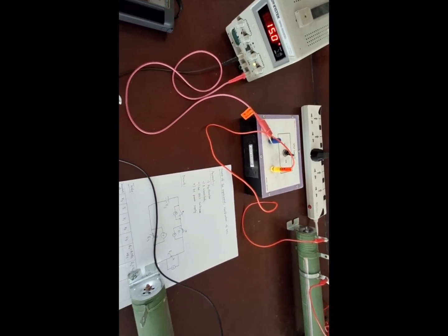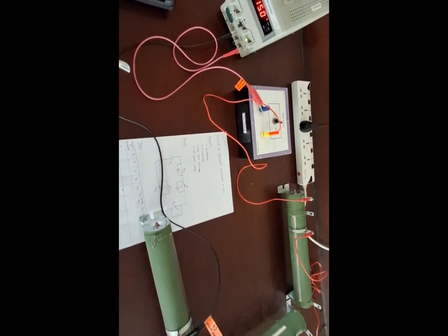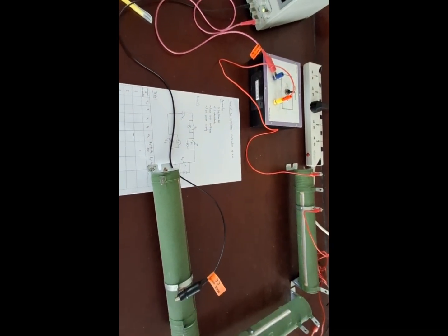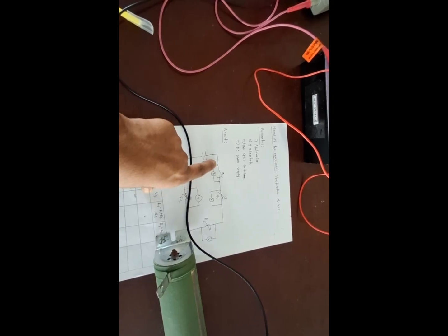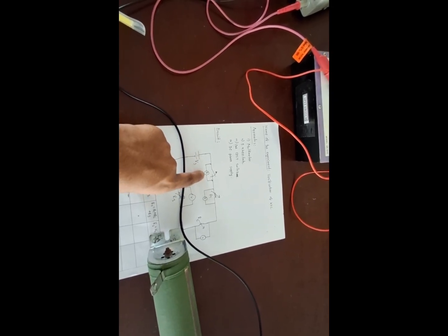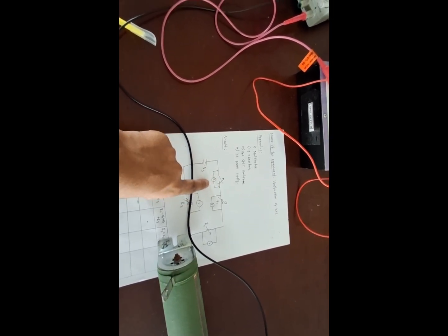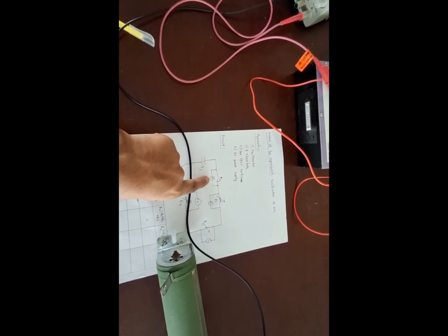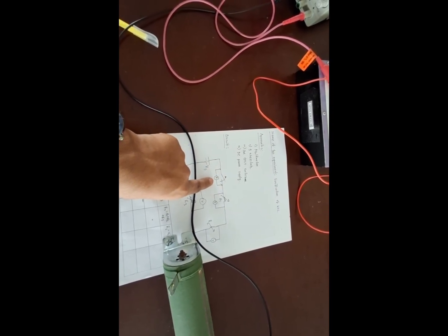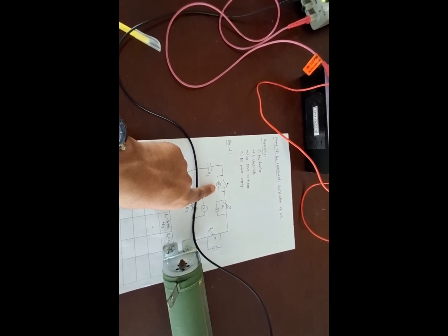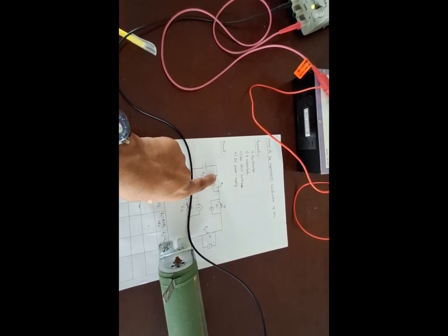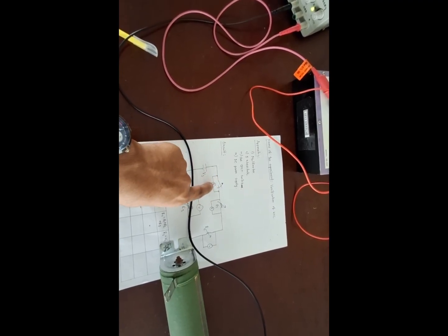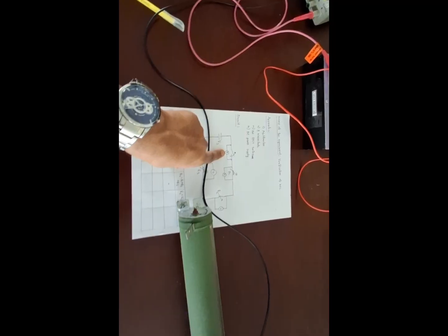Now we will measure the current flowing in the whole circuit. For measuring the current, we need to measure it across the switch. So here we can see that the ammeter is connected in parallel with the switch, but it is not actually like that. If we connect the ammeter across the switch, it will actually behave like an ammeter. It will actually measure the current, because if we turn off the switch and connect the ammeter across the 2 points of the switch, that will be a series connection and we will get the measurement of current. So let's do it.